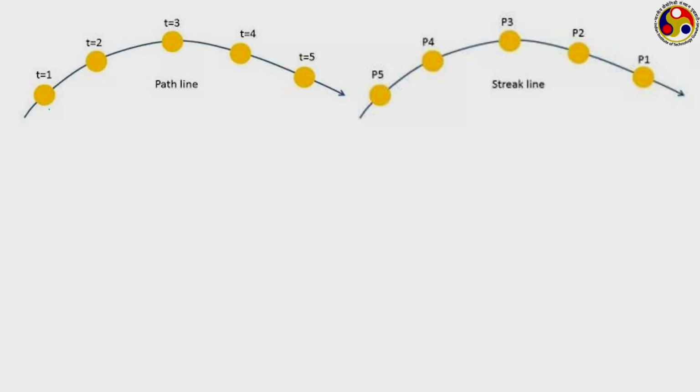Here we are keeping our focus on a particular particle and just seeing how it is moving. So here, say this is the particle, then we are just tracking the movement of this particle. Let us say at t equal to 0 the particle is somewhere here, then we are tracking its movement over a period of time, and the locus of this is the path line. So this is the locus of this particle over these 5 or 6 seconds shown here, and that is the path line corresponding to this particular particle. It is in a way the Lagrangian way of describing the flow field, because here we are engaging ourselves with a particular particle and moving with the particle to see which path I am able to track, that is the path line.